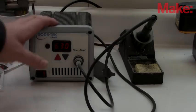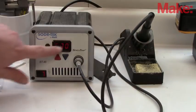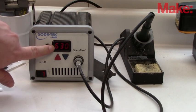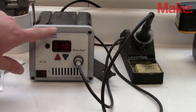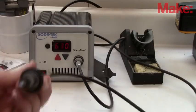Next is a soldering iron. I like a benchtop model soldering iron with multiple tips. This one has changeable tips, and this one also has a selectable temperature. I don't like set temperature soldering irons. I like to be able to raise it and lower it depending on what I'm doing.